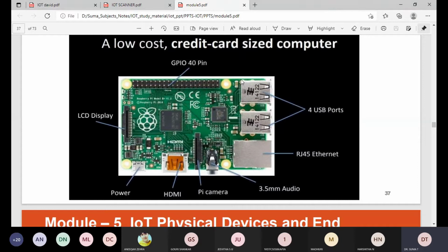In the programming environment, the GPIO board option refers to the pins by the number of the pin in the diagram below. The GPIO BCM option refers to the pins by the Broadcom SoC channel number. These are the numbers after the GPIO in the green rectangles on the outside of the diagrams below. And you can see the LCD display, right?